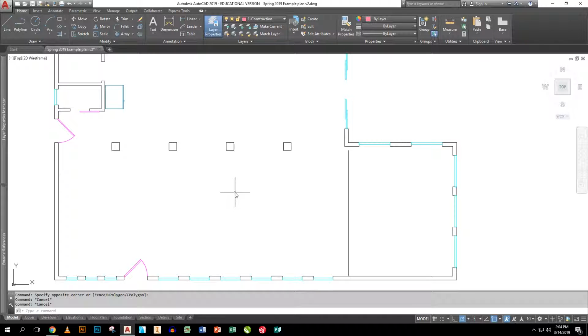Now, that evenly spaces them. What's the spacing? I don't know. I didn't have to calculate it. So let's do a quick distance. If I go from corner to corner, the distance in between those is 6'4" and 13/16 of an inch. Okay, that's great, but I don't know a cabinet maker that's going to hold to a 1/16 of an inch.